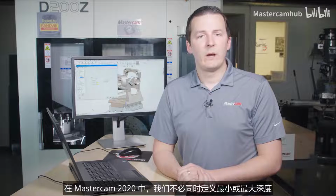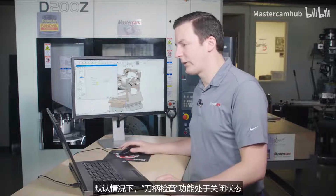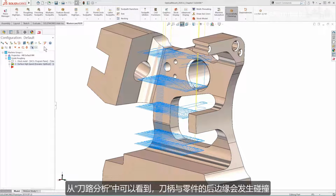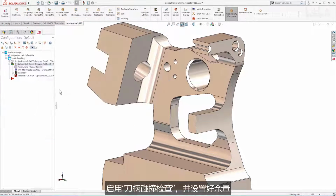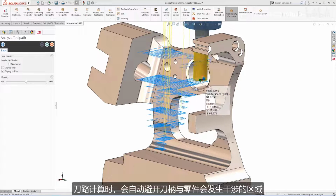New for Mastercam 2020, we don't have to provide a minimum or maximum depth if we don't want to, which saves us from spending time on unnecessary steps. Holder checking is turned off by default. As you can see from this Analyze Toolpath image, the tool holder collides with the back edge of the part. If we re-enter the toolpath parameters, toggle on tool holder collision checking, and add an additional clearance value, the tool motion is trimmed down to areas where there are no collisions.